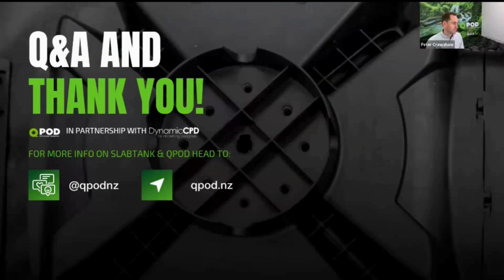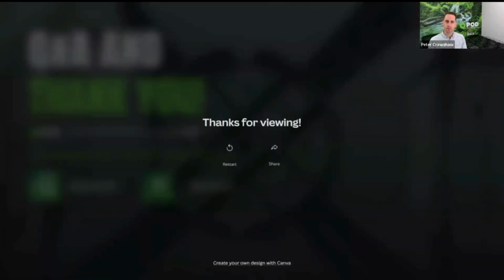Nice. Perfect. Thanks, Peter. Is there a maximum cover under driveways, for example, for steep sites? Maximum cover, so it might be topping cover. That's 100 millimeters of concrete is our guidance there. For steep sites, that raises another challenge. If you've got steep sites, you might be staggering the tanks down, which I'm not quite sure how well that would work, to be honest. You'd get a lot of head in the top tank. So a little bit of creative thinking there. It probably would need to be a specific engineered design, which we need to have a look at.